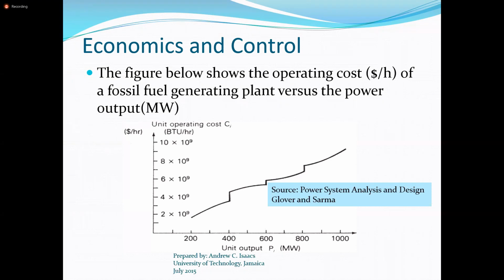V and delta? And so the concluding statement must be, one, the load angle is impacted more readily by changes in the active power at the bus bar. That's conclusion number one.